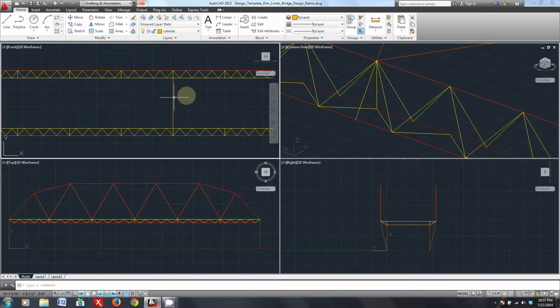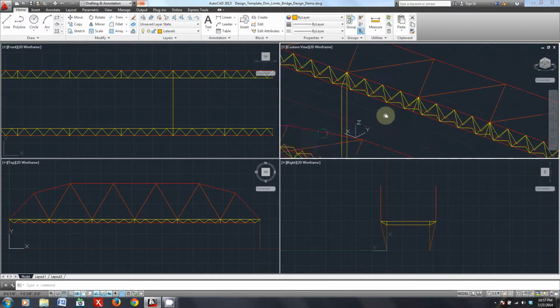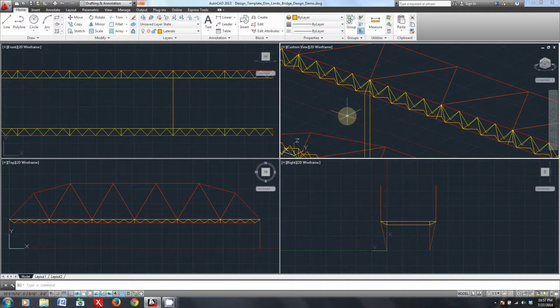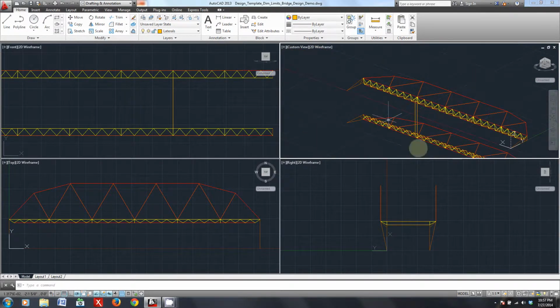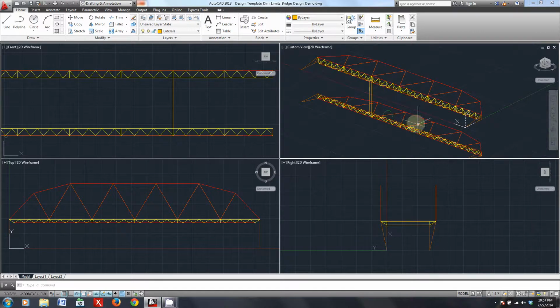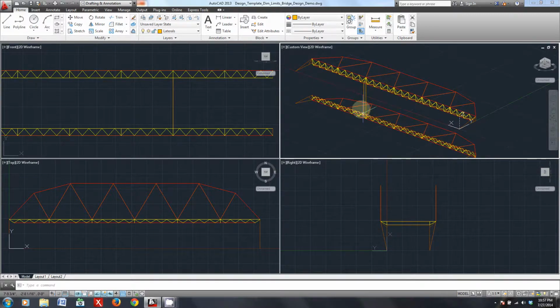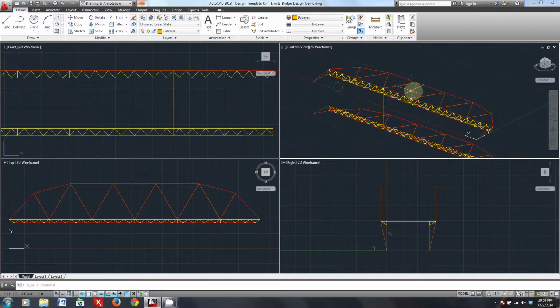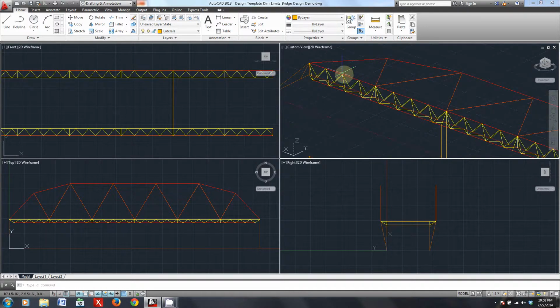So my best advice is, if you're moving things around, selecting base points, copying things, stuff like that, try to do that all in 3D. Even drawing, I prefer to draw in the 3D viewport, just because there's no ambiguity about which lines are being connected between which points.